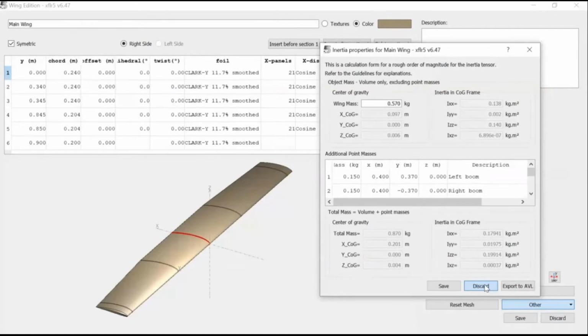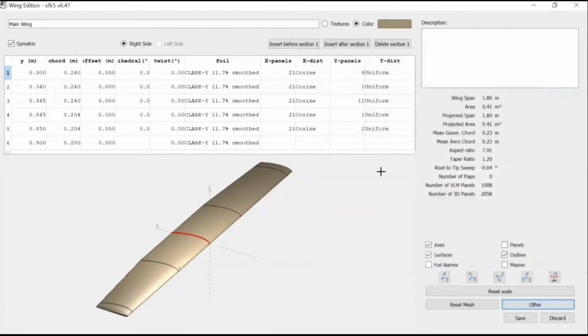For flaps definition, we must use the flap deflected airfoils defined before. We change the airfoil only for the affected span and leave the neighboring gap section airfoil unchanged as seen here.